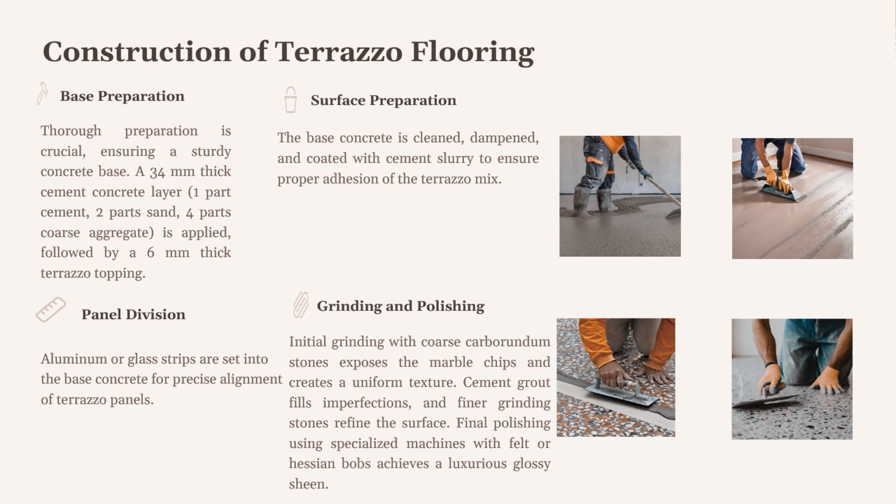Once everything is set, the base concrete is cleaned, damped and coated with cement slurry to promote adhesion. Then comes the artistic part, the terrazzo mix. It is a carefully proportioned blend of cement, marble chips ranging from 3 mm to 6 mm in size, and water. This mix is poured and tamped to ensure the marble chips are evenly distributed and the surface is level.